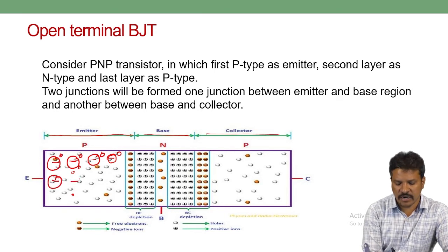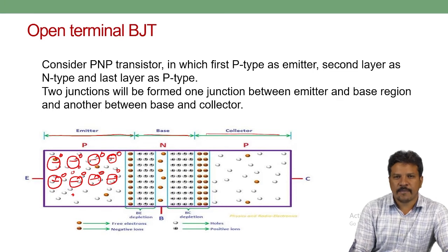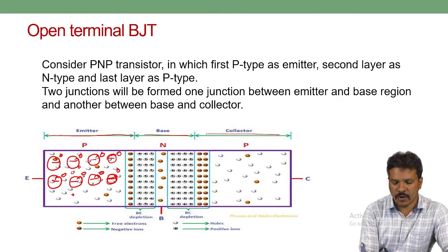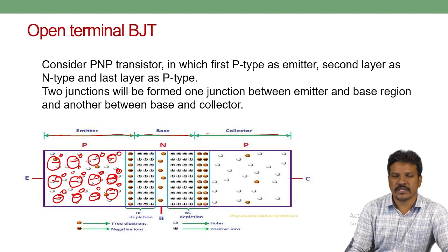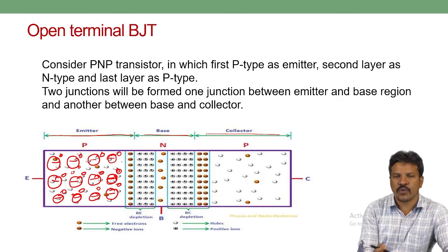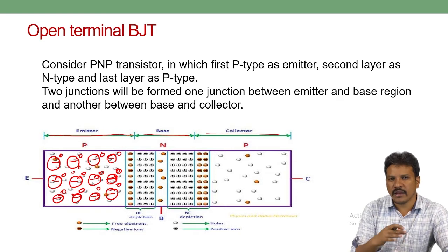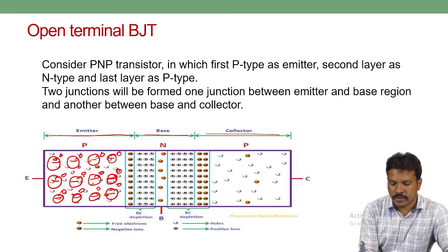This kind of representation for p-type material is that acceptor atoms, trivalent atoms, are added to an intrinsic semiconductor to get the p-type. This minus with circle represents this added trivalent atom with a vacant space called a hole. This p-type has excess holes, and whenever this semiconductor material is excited, these excess or free holes are first excited. When it accepts one electron, it fills the covalent bond and becomes a negative ion.